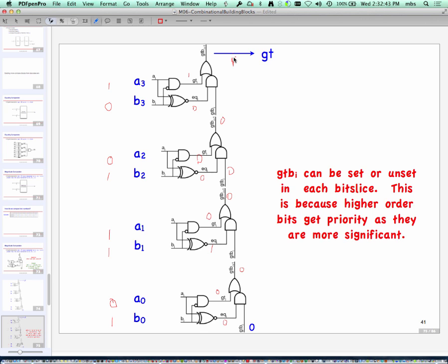The XOR bit, what is it without the little knot in the front? What does an XOR do? You tell me, someone. If XNOR checks for equality, what will XOR check for? Non-equality, right? So that's one way of looking at it. The other way of looking at it is saying that one and only one input is 1. Okay. Now for the 2 input case, that is indeed the thing.